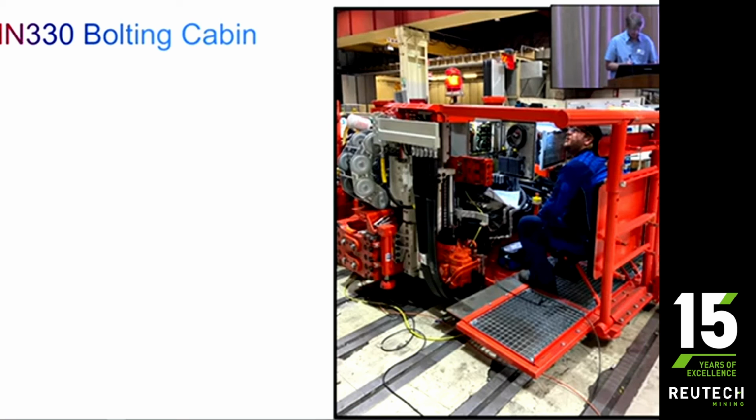This project, we call it our Digital Ground Control Management Plan. People talk about digital twins of the mine. So we're collaborating with a university in Australia, and the idea here is to build the mine as is, digitally. We've taken one of our shafts, and we've literally built the mine like that, all the structures, all the stopes, everything in 3D. We've plotted all the brown squares where we've had falls of ground. In this case, the spheres are where compliance checks have taken place.